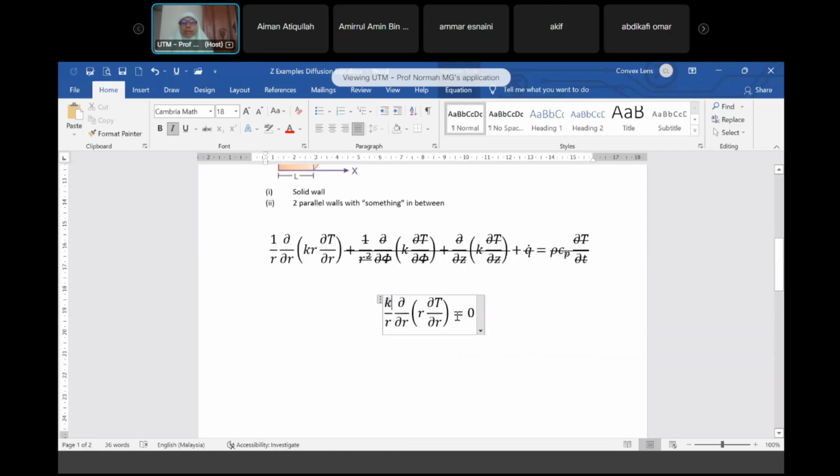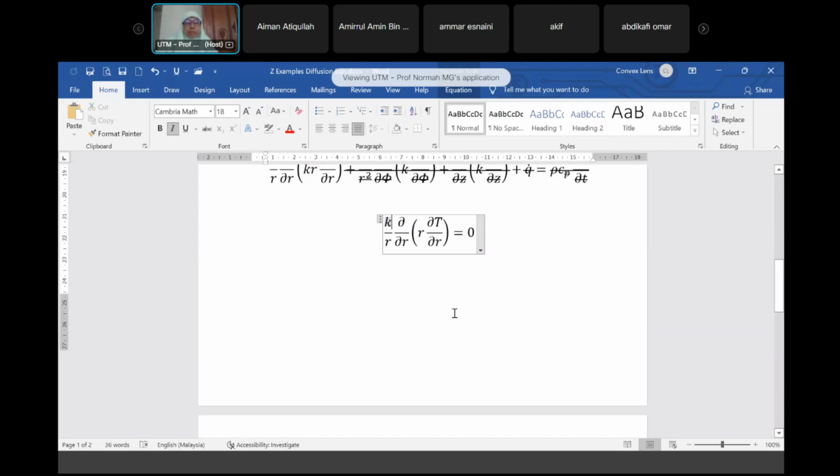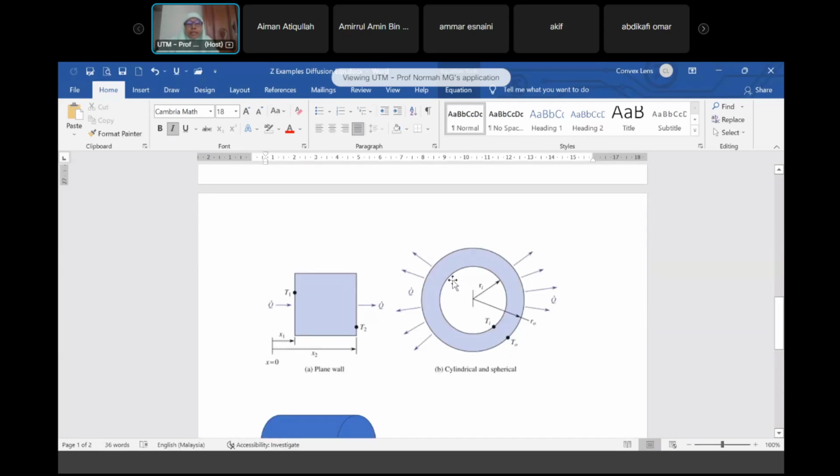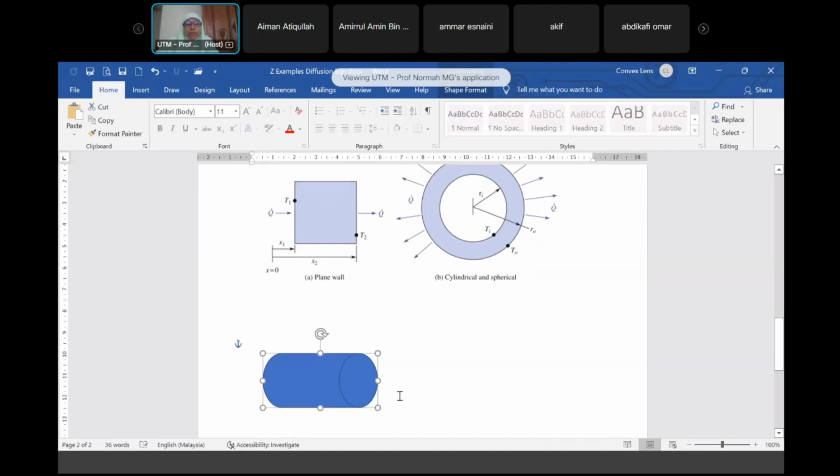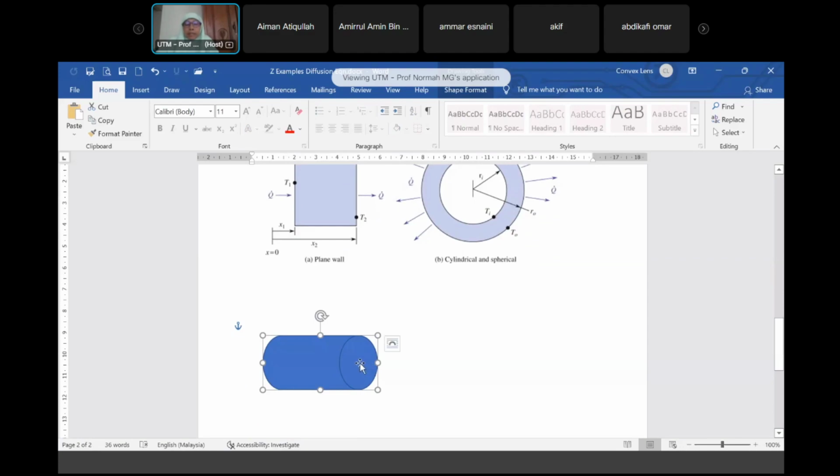So here you have, can you solve this? Yes, you may be able to solve this. If it's a solid cylinder, then you have boundary conditions on the outer wall, and the one right in the middle would have dT/dr equal to 0, because the derivative in the middle of a solid wall, symmetric in theta, is 0.